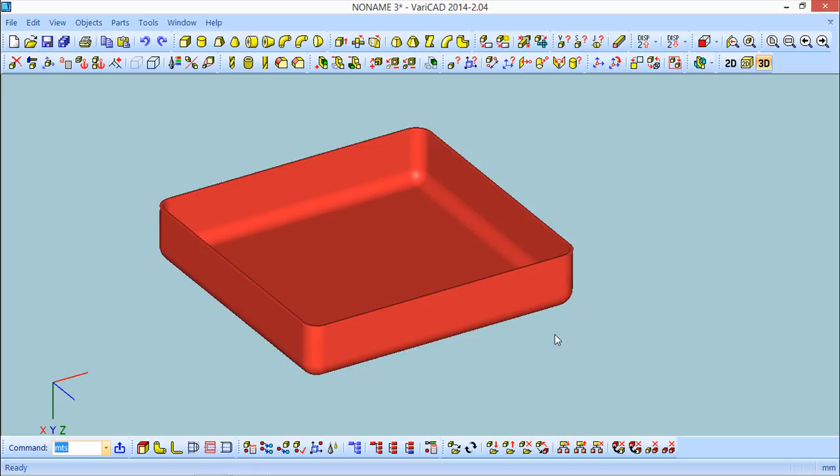And if we have those relations done, and on the other hand, before we have the parameters done for one part, if you change the parameters, the part will change and the constraints will affect the surrounding parts you have on the assembly also.